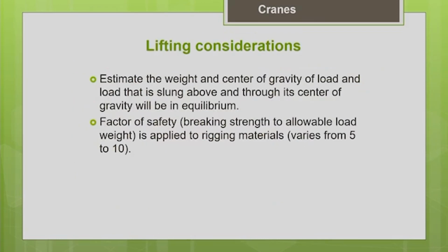Another important thing is, when you do the rigging of the load, it is better to find the center of gravity of the load and rig it at that point, so that the load will be in a stable equilibrium, from the safety perspective. This is another guideline, and many times you can see that some accidents happen because of rigging failure.